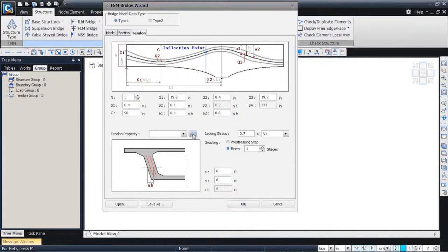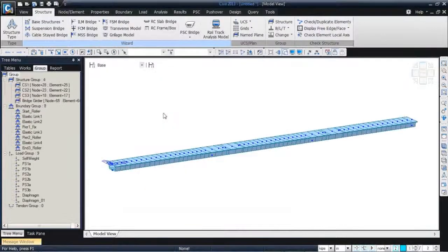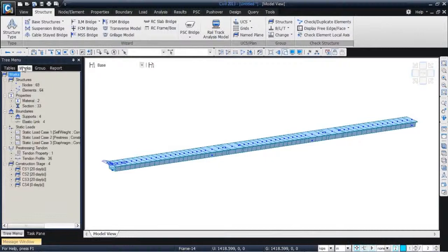And in this manner you can create exactly the same bridge but with a different construction methodology, and the difference comes in the wet concrete weight. If you recall, earlier we had a wet concrete weight coming at a particular location because of the movable scaffolding system, but since now the construction is fully shored from bottom, you have a fully supported system, so there is no need of extra reactions on the adjacent members.